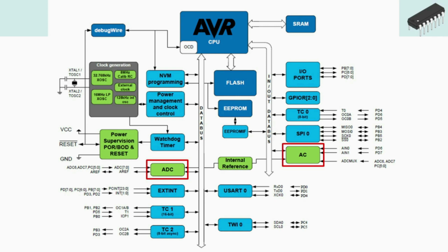The microcontroller supports 6 sleep modes. Sleep modes are used to save power by enabling applications to shut down unused modules in the microcontroller. The various sleep modes allow the user to tailor the power consumption according to the application's requirement. The power management of the ATmega328 supports brown-out detection. The BOD circuit monitors the supply voltage and resets the microcontroller when the supply voltage falls below a predefined threshold. The trigger level of the BOD is selected by the BOD level bits in the extended fuse high byte.